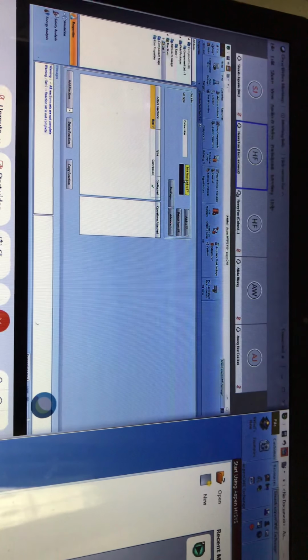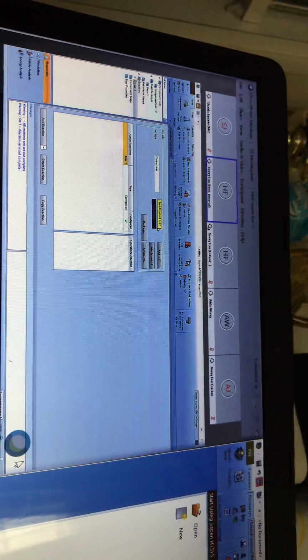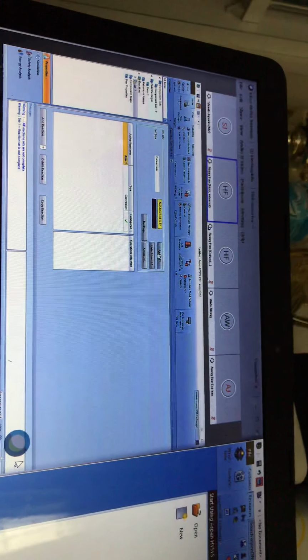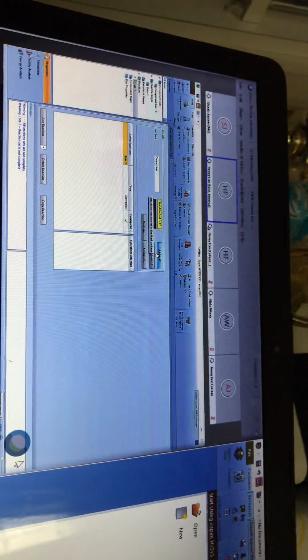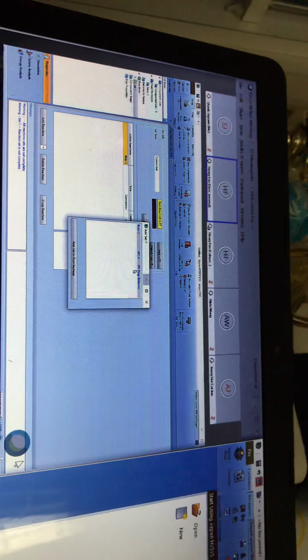You can see we still have a yellow warning here. It mentions not attached to FP. FP here normally stands for fluid package. This means the reaction that you defined is yet to be attached to any fluid package. Okay, so you need to click Add to FP. Click the button next to it, then in this file we only define one fluid package with Peng-Robinson.